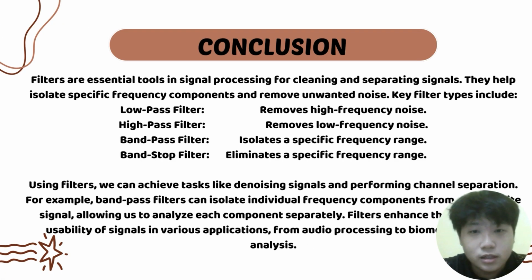So in conclusion, filters are essential tools in signal processing for cleaning and separating signals. They help isolate specific frequency components and remove unwanted noise. The key filter types include low pass, high pass, band pass, and band stop filters. The low pass filter removes high frequency noise, allowing only the low frequencies to pass through. The high pass filter removes low frequency noise and only passes the high frequency signals.